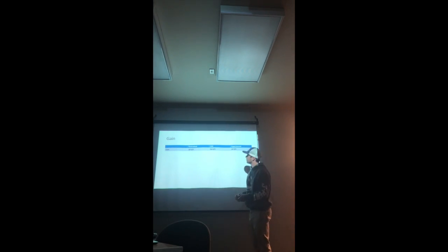For the gain, for theoretical, 10 volts per volt, that's what we designed the whole circuit for. CAD is 9.8, it's really close, it just has a little more real world stuff in CAD, so that's why it's not exactly 10. Experimental, we got 34 because our output looked really good. Our output was like 9.8, but our input was 0.28 on the emitter, so that made the gain just huge when you divided those. So overall, our theoretical and CAD looked really good, but because this was such a tough circuit with transistors and it's easy to short circuit them using the probes and stuff, we weren't able to get great experimental values, but our circuit was working correctly.